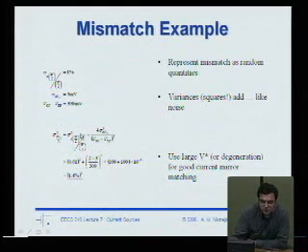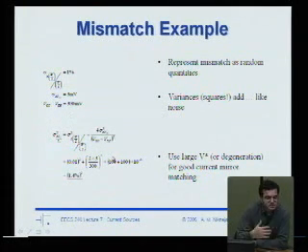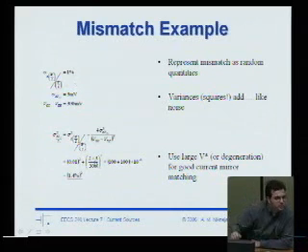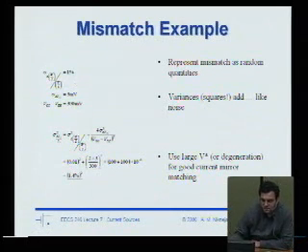So what you'd like to do is bias your device with enough overdrive voltage so that the overall mismatch is within some spec. In this case, 1.4%. If you do the math, you have to put 300 millivolts on your device to get 1%, so that 1% plus 1% is square root of 2 times 1%. So we get 1.4% overall mismatch.